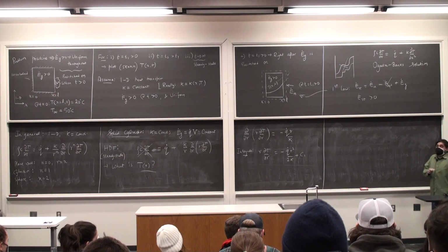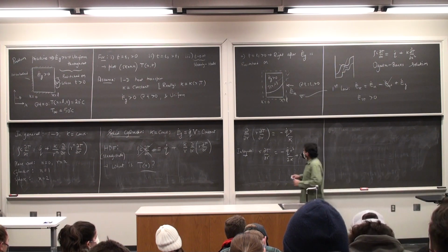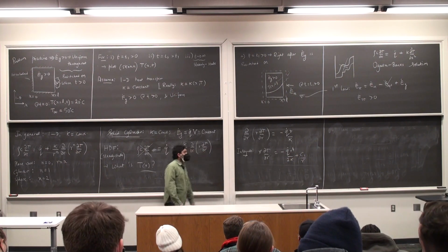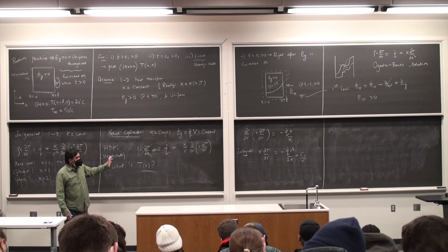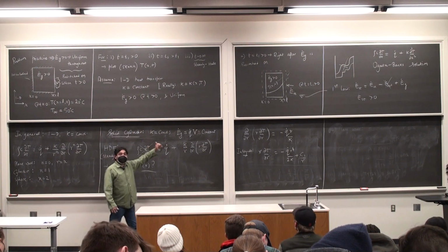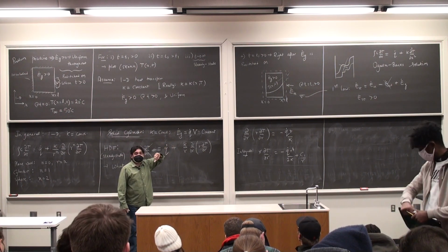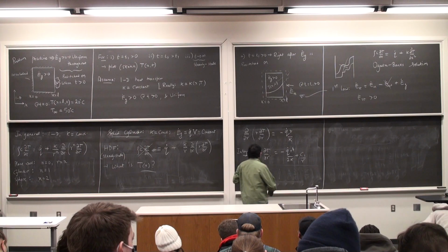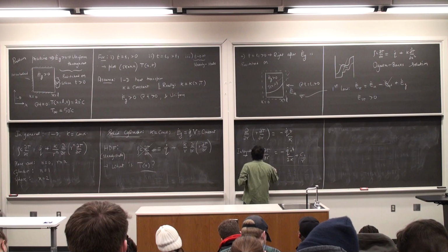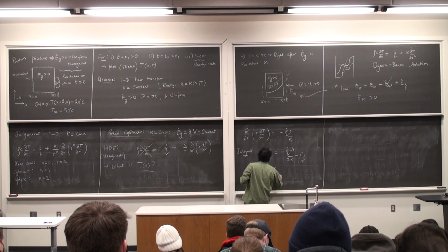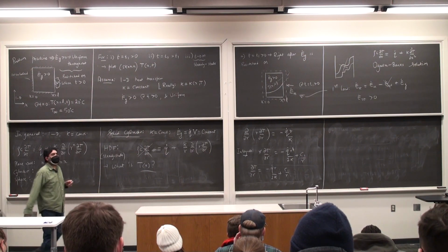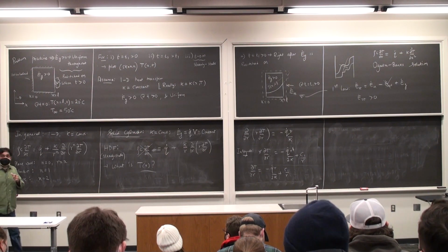Now I can take this r on the left hand side and spread it out. So if I take this r, I get a bar. I don't have an r on the left hand side, I'm just taking it out, cancelling off one of them from the r square, and then c1 becomes c1 divided by r. Then integrate one more time. So now I have dT by dr is minus q dot r by 2k plus c1 divided by r. Okay? Integrate one more time, both sides.